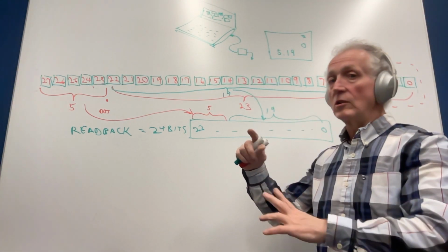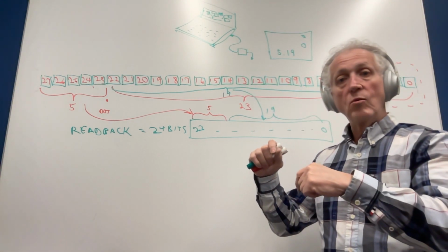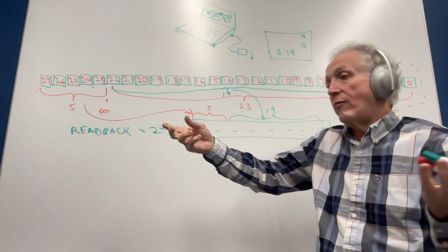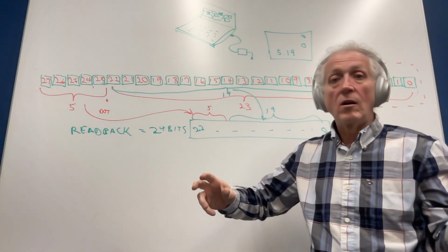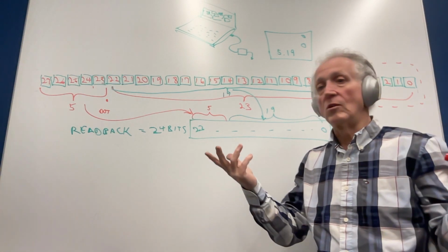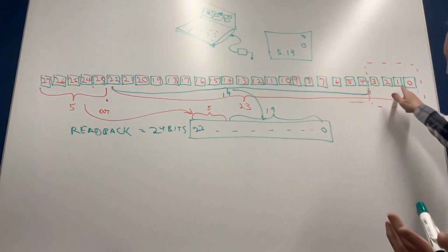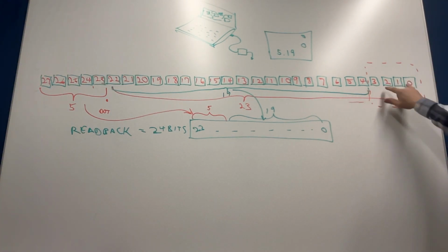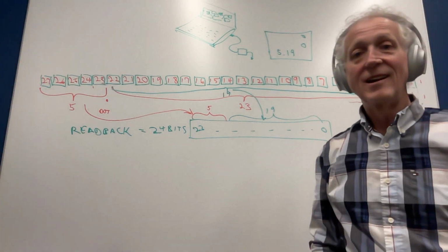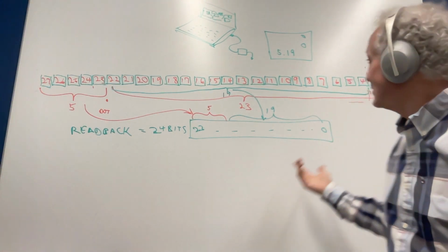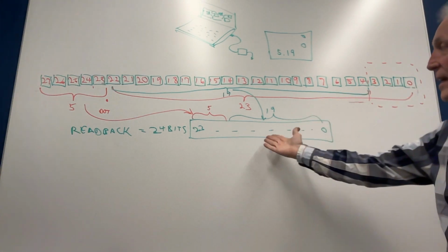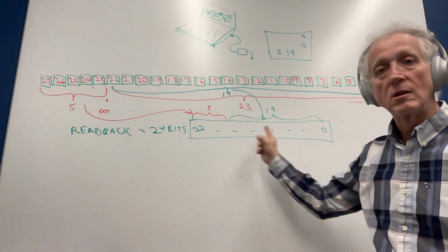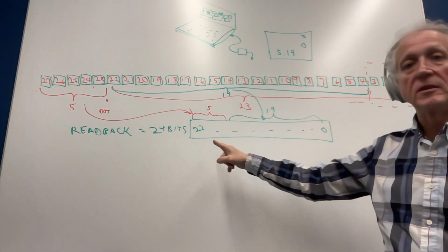But when you're working to control a mux and you want to see what the position is, you got to switch a mux. And you got 5, 6 different positions, maybe 10 positions. A lot of times it's only 3 or 4, but we're using an integer. So it's 0, 1, 2, 3, 4. It's all these four bottom bits. It goes up to 15. And so we can't see it. It won't show up. It'll all be zeros, even though it's changing.